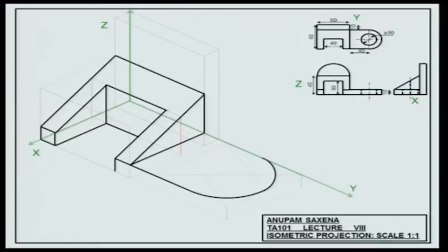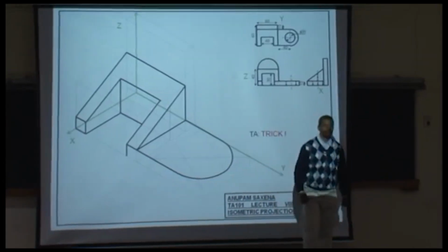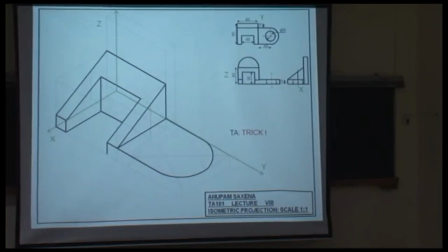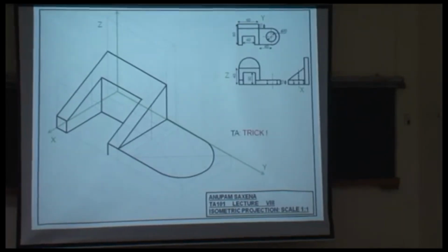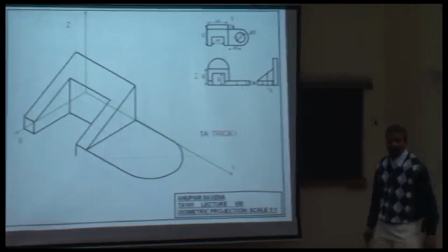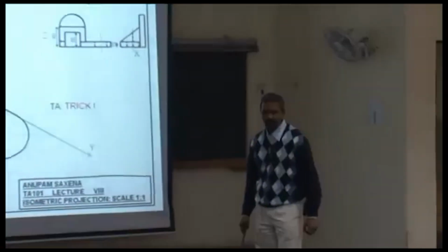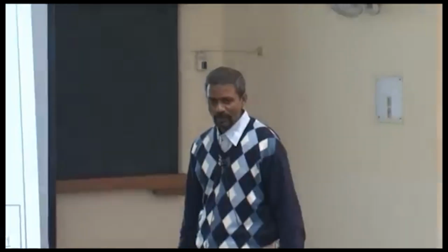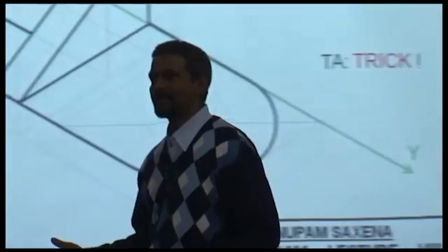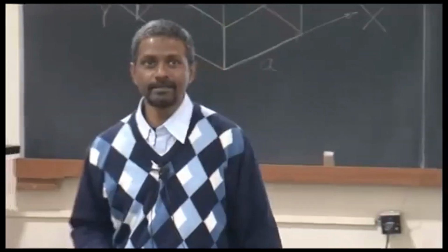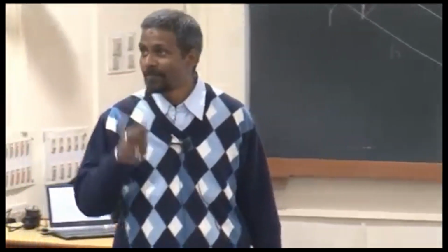Here comes the trick. What do you say we are going to be seeing here? A parallel ellipse. We'll draw vertical line tangential to the ellipse, and we'll draw that till that vertical line. Now, do you think that drawing a rhombus to draw that ellipse would be a good idea? No?